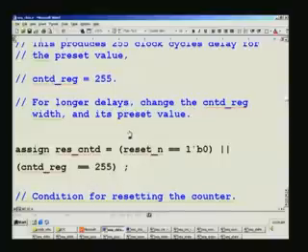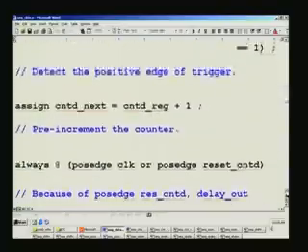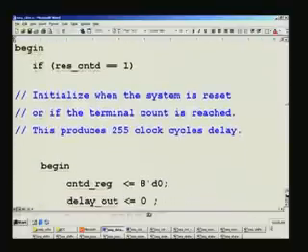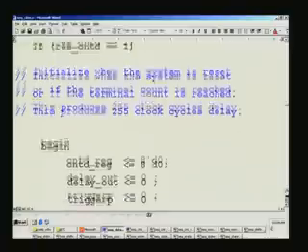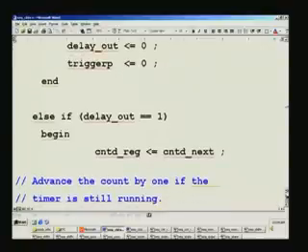Now earlier what I had done is I did not combine this. Why I combined here is I have also said always block is priority encoder, therefore we have to limit the number of ifs, else ifs to less than 4 or 5. By combining the two I have reduced by 1. So that is the advantage, thereby speeding up the operation, and of course with a little understanding complexity which we have already cleared.